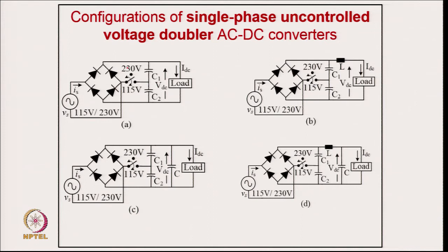So you can put the switch upper and operate this converter with 230 volt, but the output voltage will remain almost the same in that case. So your load will not be affected. In all these appliances which you might be operating, this is one of the simplest, lightweight, low cost solutions, compared to otherwise using a power transformer, which is bulky, costly, noisy, as well as lossy.